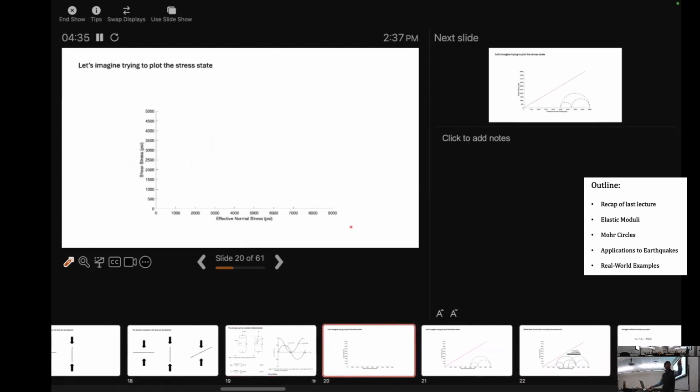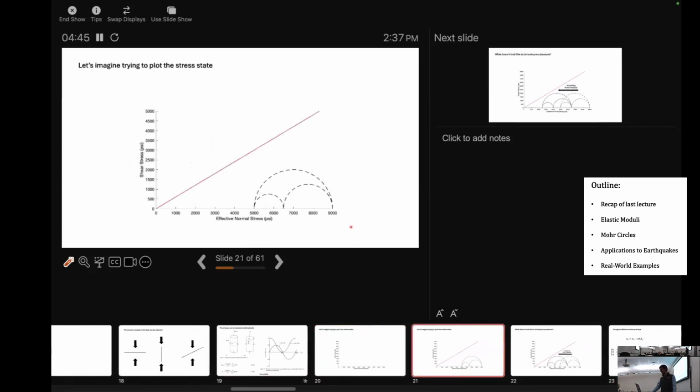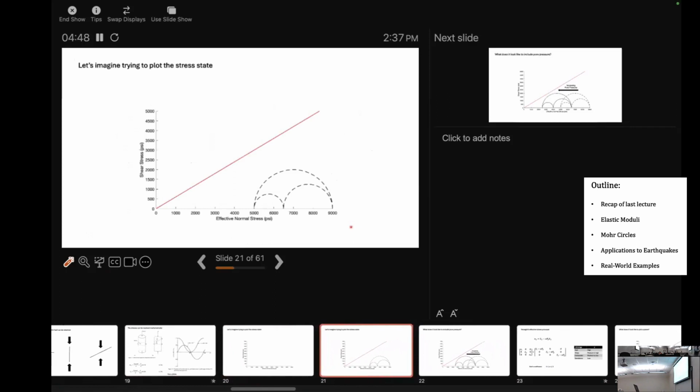So these are the axes that we just drew a circle on. Essentially, all of that was just drawing a circle or even a semicircle. And Brian gave a thumbs up, nice. And so this is a realistic representation of a Mohr circle for a geomechanical analysis. You'll notice there's something a little different about this one than our one. One is that the beta isn't exactly at 0, which is fine. The least principal stress does not have to be 0. The reason why it was 0 in our case was because we were only applying a single stress.